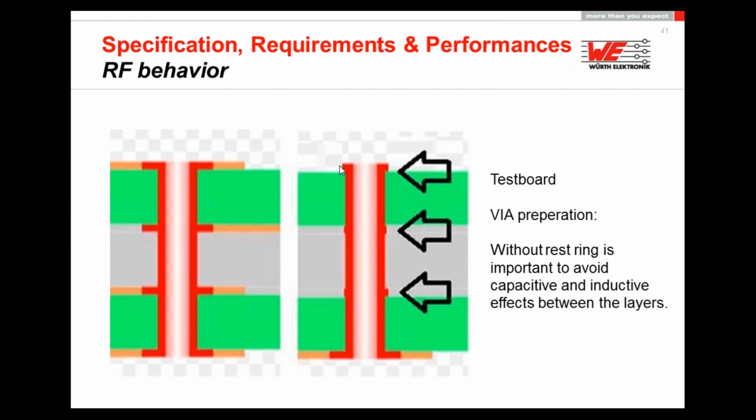That means that we will reduce the mechanical performance a little bit. That's the reason why PCB designers mostly recommend having a rest ring. But here we still have to keep our RF behavior and the speed of the signal lines in mind. So in that case, it will disturb us.